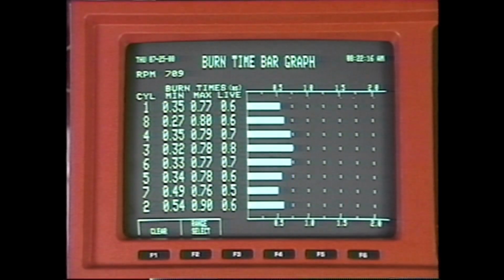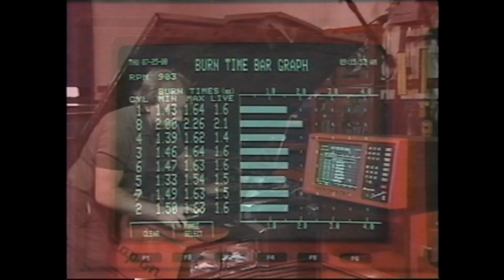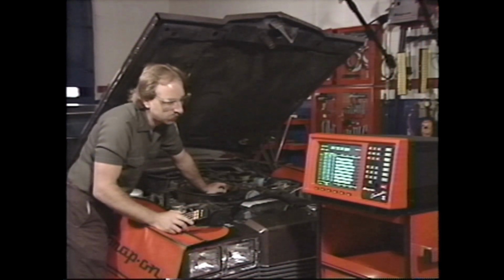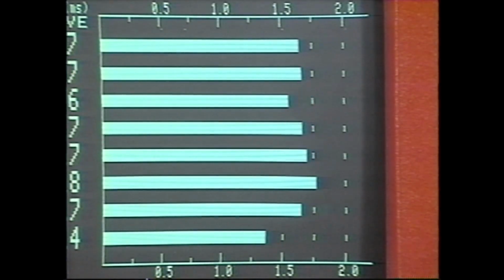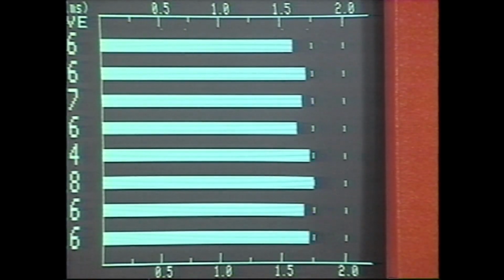Short burn times can be caused by excessive spark plug wire resistance, a wide rotor air gap, a wide spark plug gap, or an air-fuel mixture that's too lean. Long burn times can be caused by a fouled spark plug, narrow spark plug gap, or a shorted plug or wire. Emission controls that keep the air-fuel mixture lean may cause combustion to stop even though unburned air-fuel mixture is left. In these engines, burn times should be longer because the spark must be sustained for the duration of combustion.